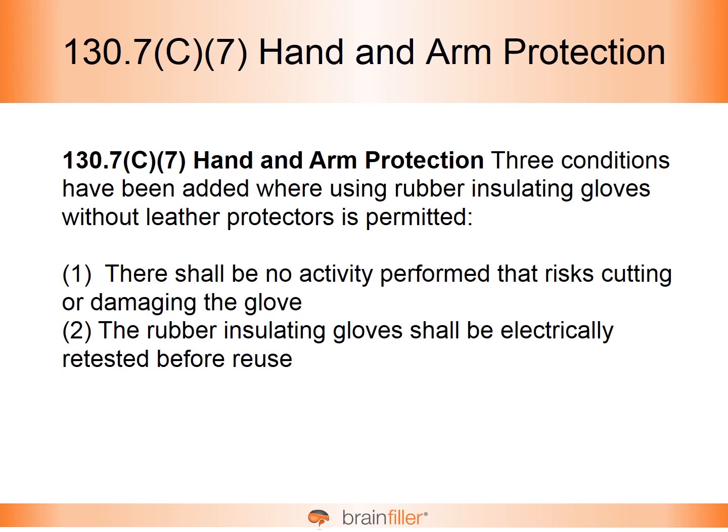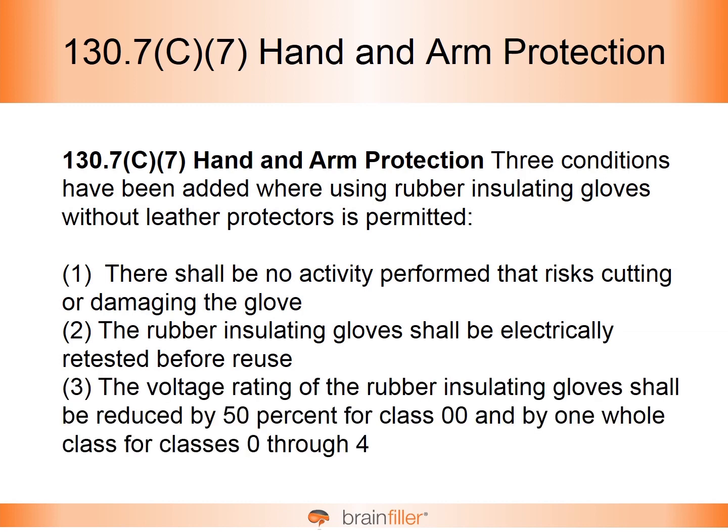Number 2, the rubber insulating glove shall be electrically retested before it's reused. And number 3, the voltage rating of the rubber insulating gloves will be reduced by 50% for class double-aught gloves and by 1 whole class for classes 0 through 4.